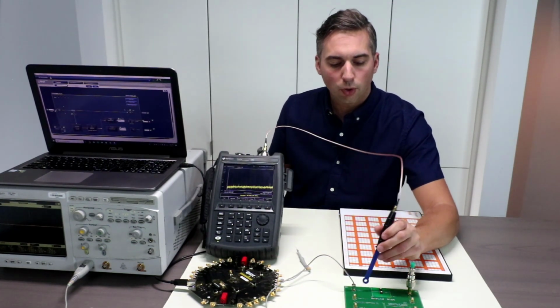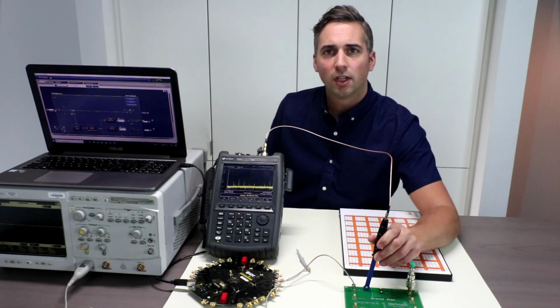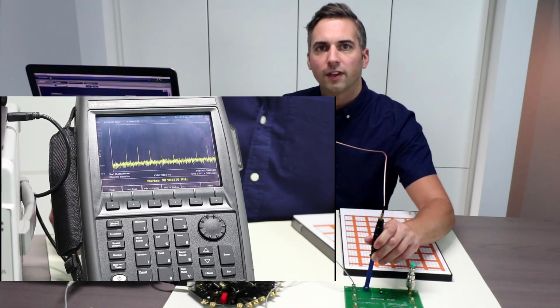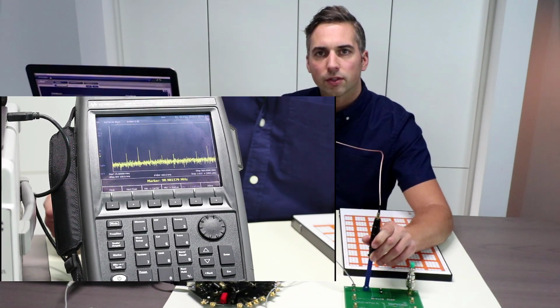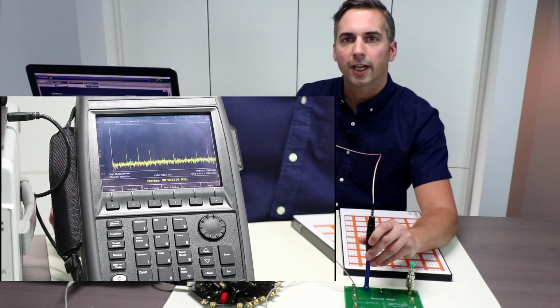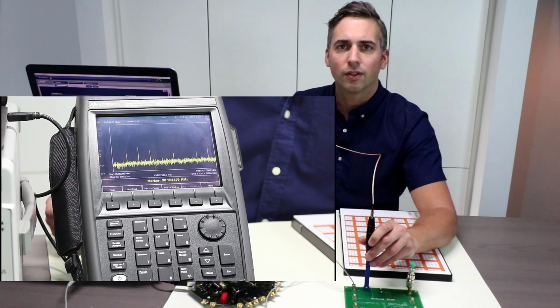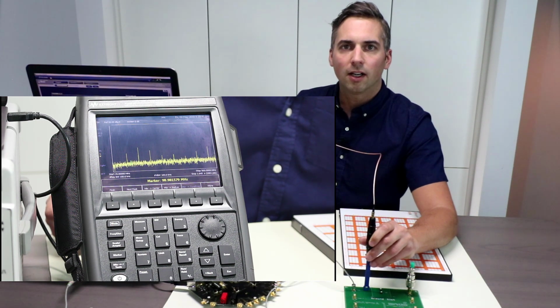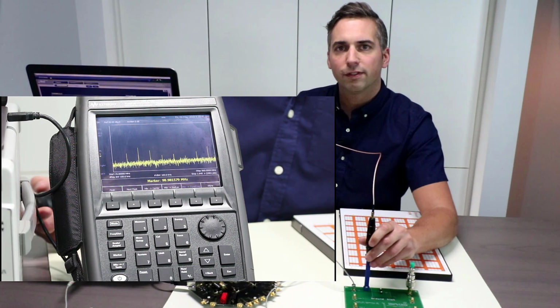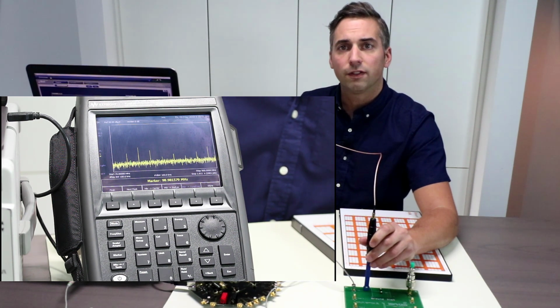So if we take a near field probe and have a look at the high frequency content of this clock source, what we can see is that not only the 25 megahertz fundamental frequency is visible, but also the harmonics that extend way up into the hundreds of megahertz. Now, if you remember back to those horrible Laplace transforms you learned about at university, we actually need the harmonics, or some of them at least, to accurately recreate a square wave, or more correctly, in this case, a trapezoidal wave, since the rising and falling edges take a finite amount of time.